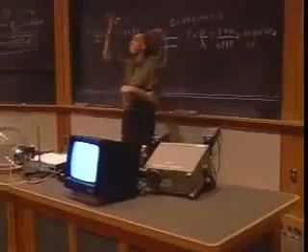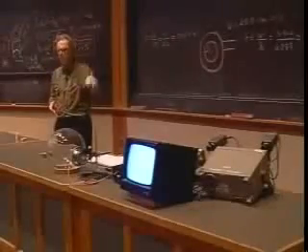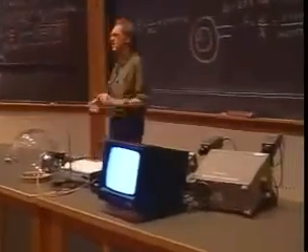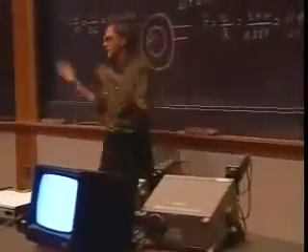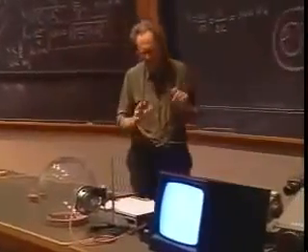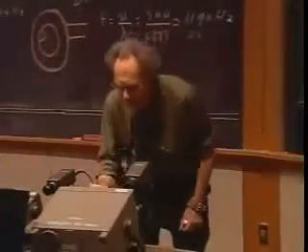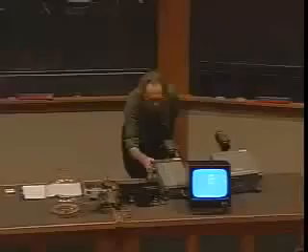Well, we were staring at each other in disbelief, and so we went on. I said to him, you know the 60 hertz are the lights in the building. That's what you pick up. It's some pickup, some crazy pickup. It's not a sound resonance. Whenever you see 60 hertz in the United States, it's pickup. If you see 50 hertz in Europe, you know it is some pickup. So I was willing to forget about it. In any case, we went on and we were trying to find the other